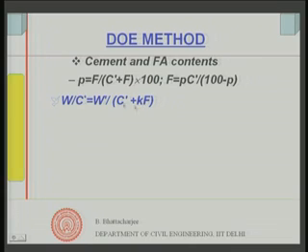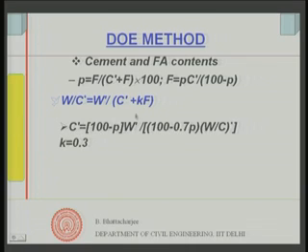If K was equal to 1, that means all the fly ash behaves like cement, but K being less than 1 tells us that I have possibly some fraction, some part of the equivalent cement. If F is the total fly ash present in the cementitious, then F into K, with K taken as 0.3, is a guideline. One can decide his own K from their own test, but K of 0.3 can be a conservative value. One can start with this, but then determine his own K and find out as it changes.